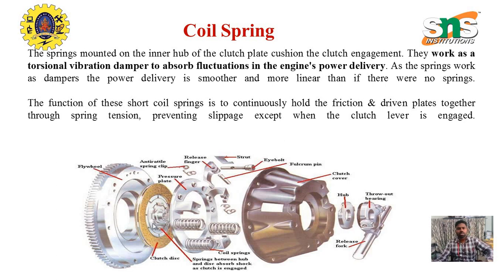As the spring works as a damper, the power delivery is smoother and more linear than if there is no spring. So we can deliver the power in a very smooth manner, which is a special advantage over a system having no spring in the clutch.